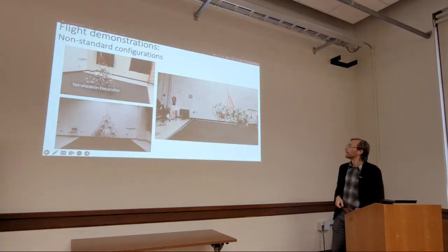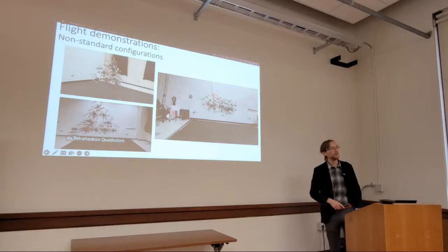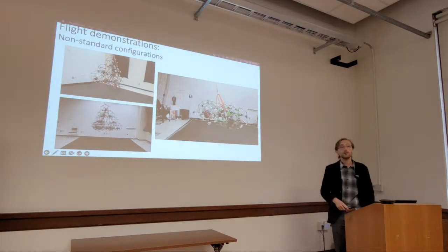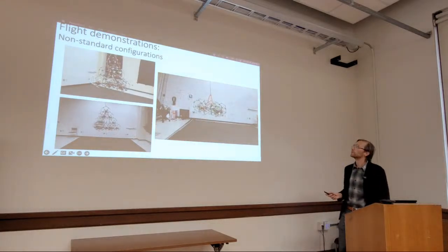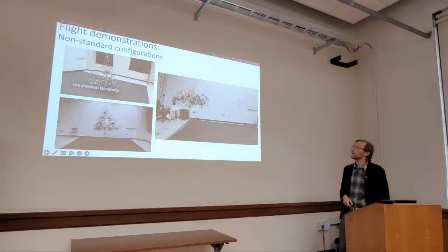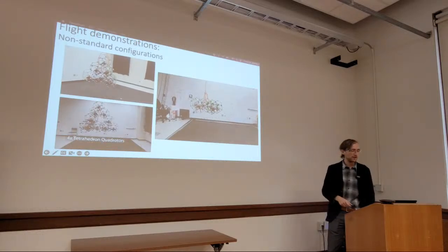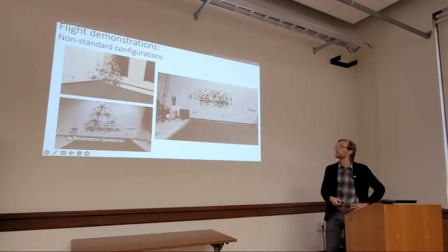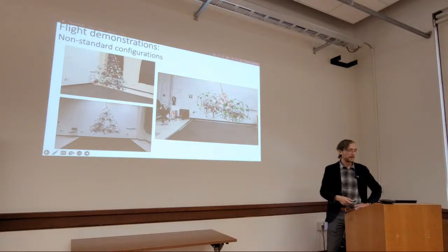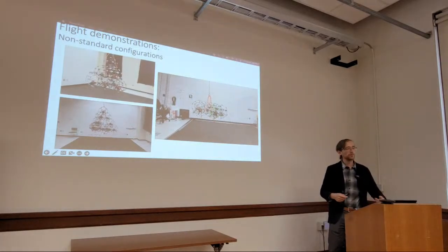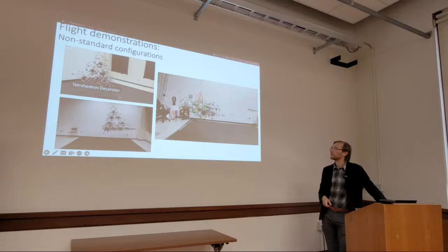And this one, well, I don't know if we can talk about controlled flight, but it can lift its weight. But as you notice, the angle of the propeller is actually quite high. It's about 15 degrees, which means, well, actually, no, it's more than 15 degrees. I think it's a little more than 20 degrees. But the fact is, there is a significant decrease in overall thrust available. And because the modules themselves are quite heavy, we barely have any margin for controlling the vehicle. So that's why it was very hard to have a successful flight with this configuration.